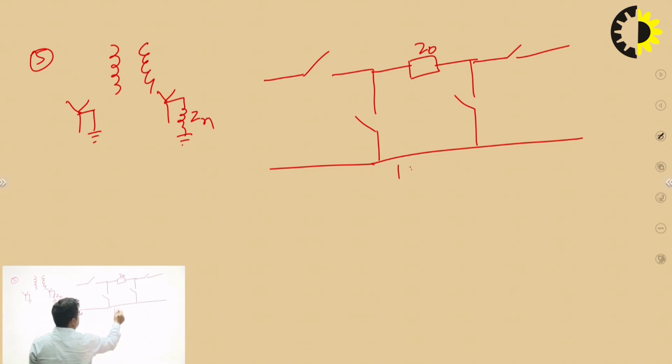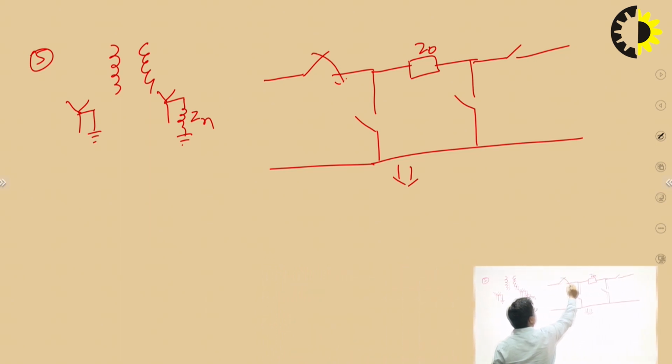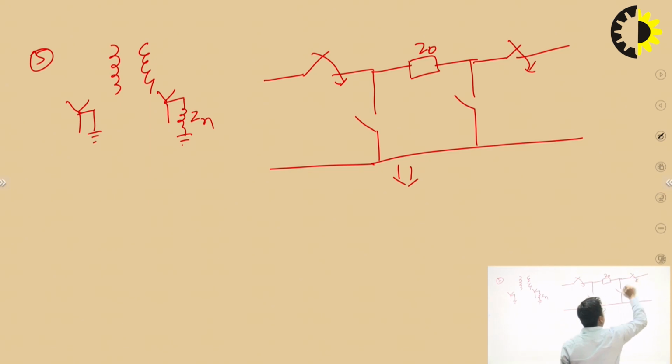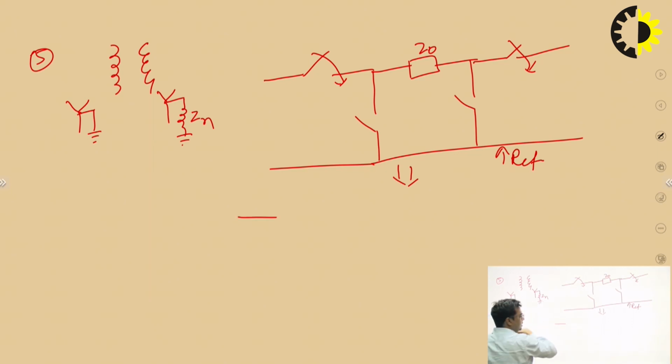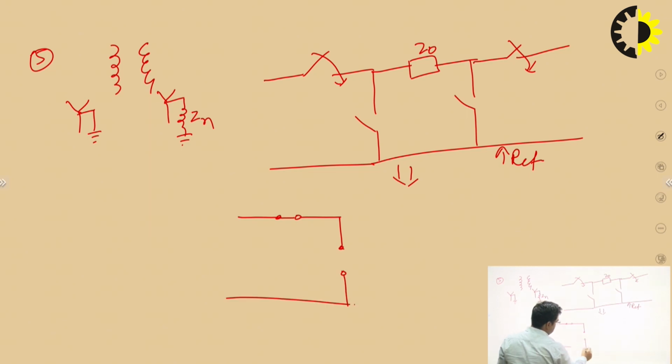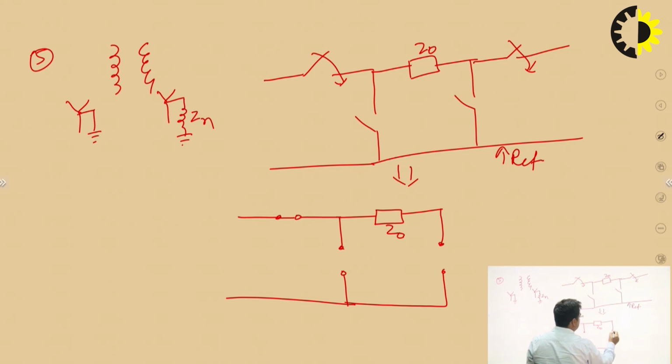We know that both sides will be star connected with grounding with some impedance. So these two are closed, and the branch connected to the reference point, or neutral point, will be open. But on the primary side there will be solid grounding, so this is simply connected with this network. This will be open, and there is the impedance Z0. This is again open, and this will be closed by the impedance, because 3 times the zero sequence current will be flowing in the circuit.